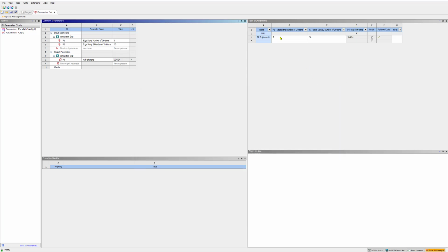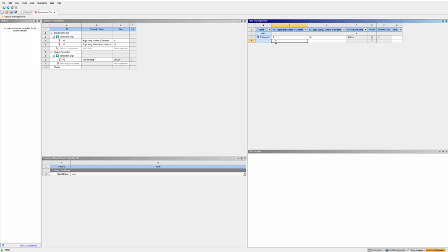This is the wall left temperature. So to do this, I can put in the new numbers. This is actually our fine mesh, but I can click here and put this value to 4, and this one to 40, and this one 3, and this time this one to 30. You just click here, double click, and then put your number.